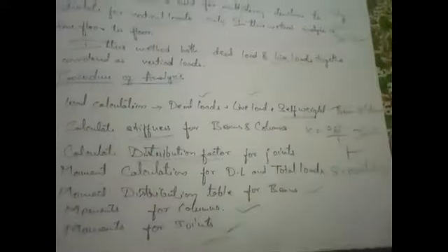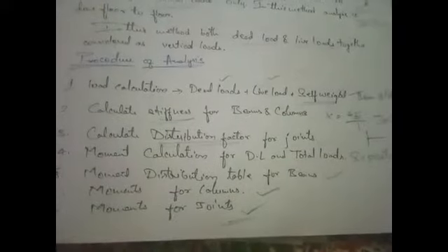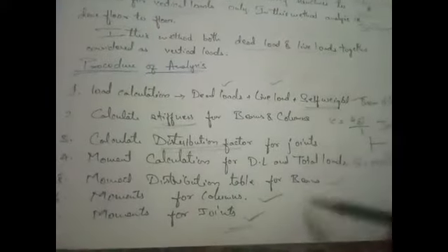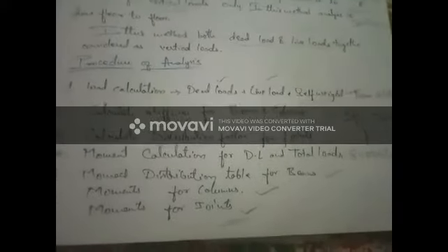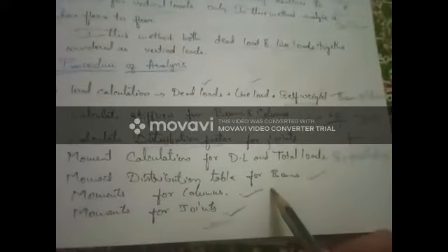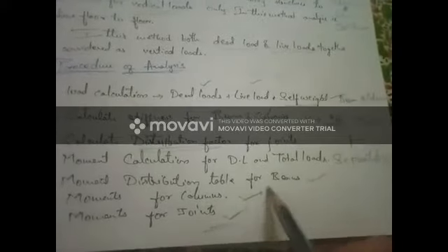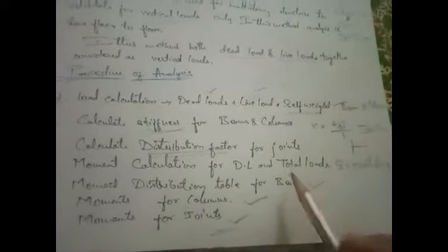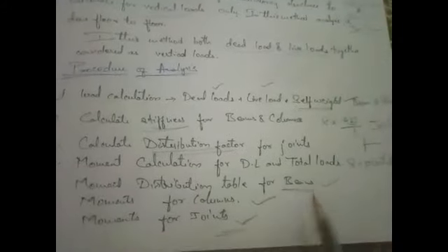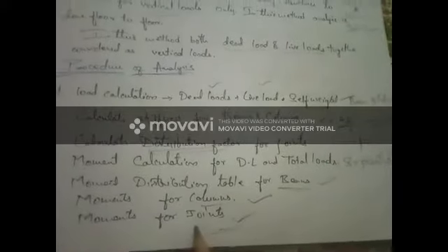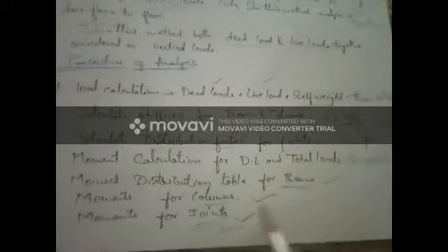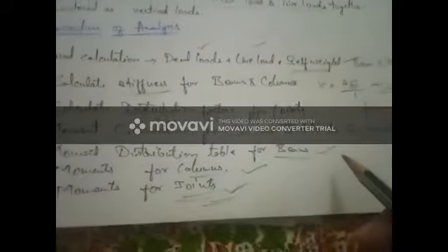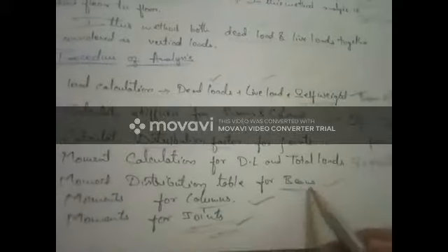Now if we go for the analysis, it looks easier. But what is the difference between the normal method and the substitution method? In moment distribution, we analyze beams and columns together in one moment distribution table, whereas in the substitution frame method, we analyze only beams separately and columns separately with respect to the joints, and joints separately. Here, in beams and columns as well, we have two conditions to analyze.